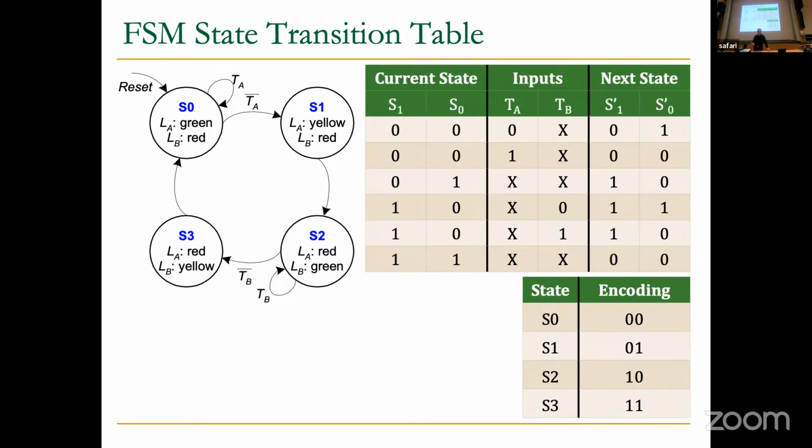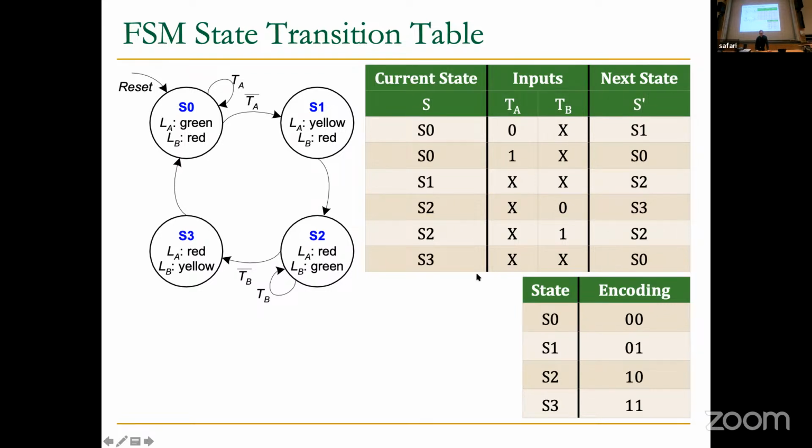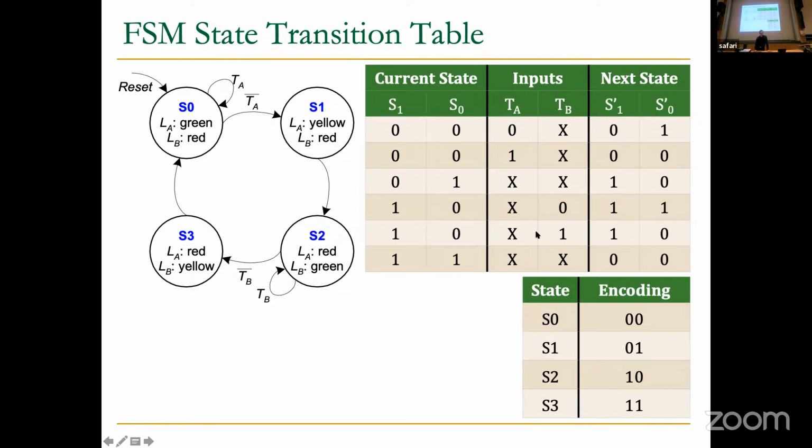Now you can actually write states as 2-bit values, let's say, that are stored in the state register. And basically, I just replaced S0 with 00, S1 with 01, S2 with 10, and S3 with 11 everywhere inside this table. Now we have a much nicer truth table. And now we can actually express this in terms of Boolean logic, right?